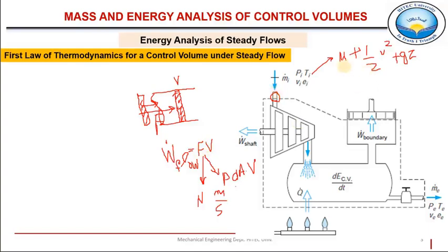So that energy is in addition to these three energies which this fluid is carrying with it, right? Now let's see. Now F is replaced with P dA into V. So now what is this, velocity into area product? That represents volume flow rate. So now this can be written as P into capital V dot. This is velocity, but this V dot represents volume flow rate, because velocity into area becomes meter cube per second. So that is the P into V dot product.